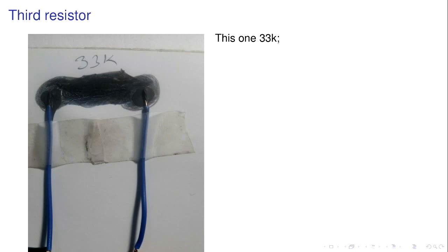You have to keep drawing until the resistance is just over what you want, and then wait for about half to 3/4 of an hour, because the resistance will keep dropping after you stop drawing. What's happening is the graphite, after you've finished drawing, actually settles and bonds to itself a little bit, and so decreases the resistance. If you go too low, just use your pencil eraser and make it back up again.